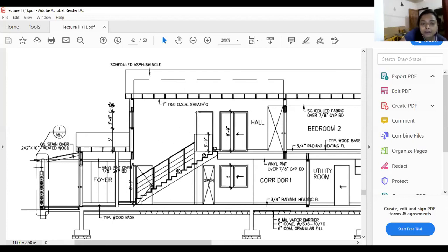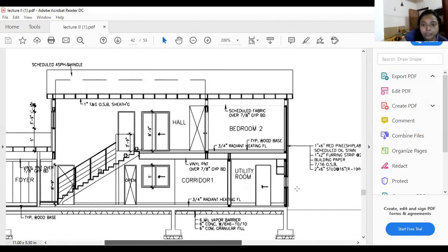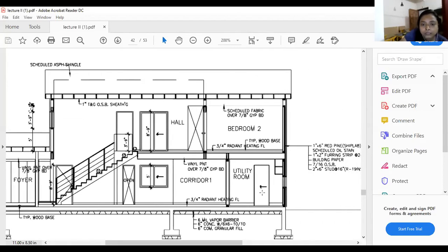So it is very easy for both the mason and the contractor to read that this represents the door and this is the railing. At the same time, he can estimate the thickness of the railing, suppose a 3-inch railing by 4-inch railing. So this represents your thickness also. This symbol shows that it is going to slide in this direction, and for this door again, if it is sliding, it is sliding in this direction.